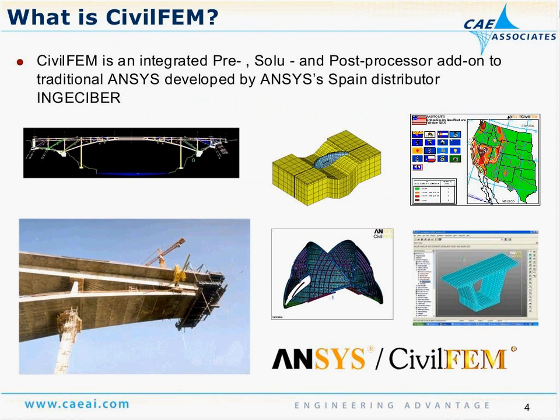So what is CivilFEM? CivilFEM is a pre- and post-processor that links into ANSYS. The CivilFEM modules create a new customized ANSYS executable such that you have access to the full breadth of ANSYS capabilities, but have a series of built-in capabilities that CivilFEM has introduced. Some of these are just time-saving routines in terms of pre-processing. Some of these are actual material models for creep, for modeling rock fracture. Some of these are for post-processing, for doing load case combinations.